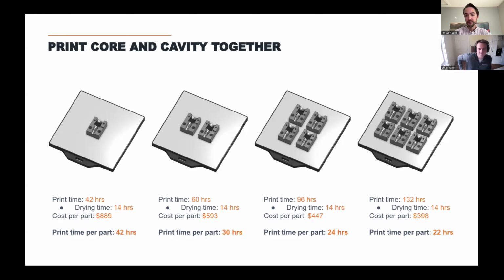We've had a number of case studies and benchmark parts we've done with partners, provided there are no overhangs on those threads, which, given the nature of our process and the manner in which the paste dispenses and our access to those underhanging surfaces, we aren't able to resolve or shape refine overhanging features. But provided you have the threads laying with the axial dimension in the X or the Y, and the parts laying flat, we do a very, very good job. Molded parts from this sample here that you see didn't have to be refined post-process. The parting line showed up quite well. So I'd say we do a fairly good job.